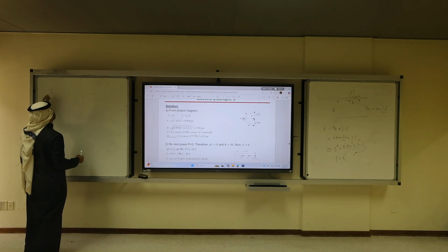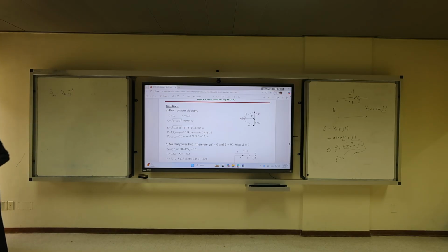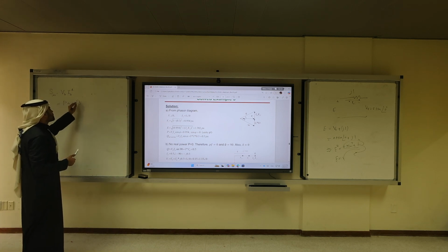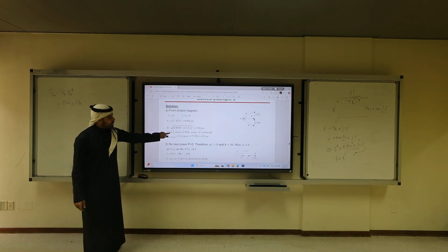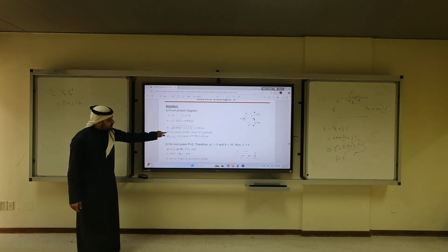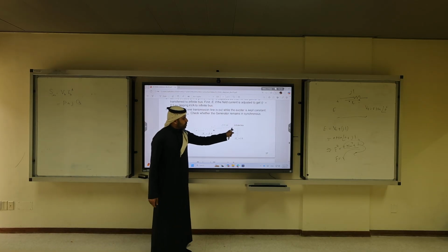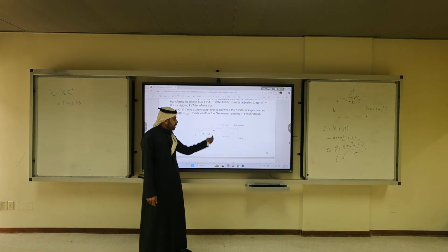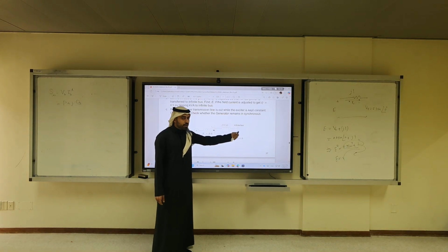What's the original equation? S at the infinite bus is what? Vb Ib conjugate. You agree with me? Yes. Which is real power plus j times the Q. The problem we have here is he is saying that the real power that passes from this point to this point would sum up at the infinite bus. So if I measure the real power at Vt, it is mathematically equal to the real power leaving.